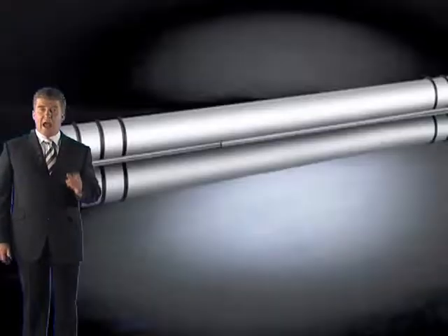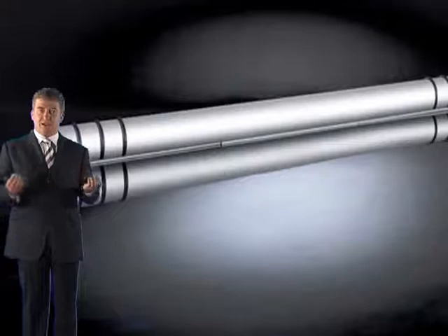Now what you have to do is ensure you specify the correct combination of curtain material weight and the bottom bar weight, so the bar itself a certain weight, to ensure that the curtain deflection remains within acceptable design limits for that particular application. Now in general, the hotter and deeper the smoke layer becomes, then the heavier the curtain and/or the bottom bar must be. So one of them's got to be heavier to hold it in place. Now this in turn can require major differences in the components. For example, you've also got to consider that the curtain might need strong motors, stronger brakes and stronger attachments to the building itself.